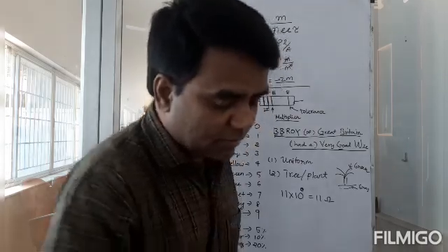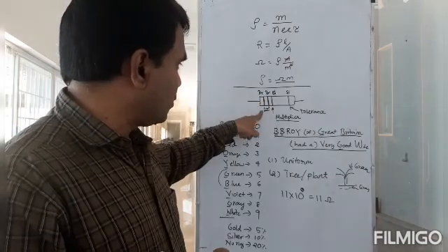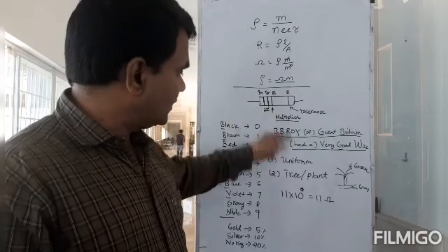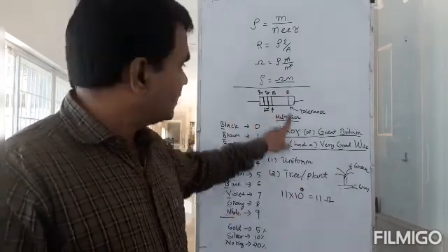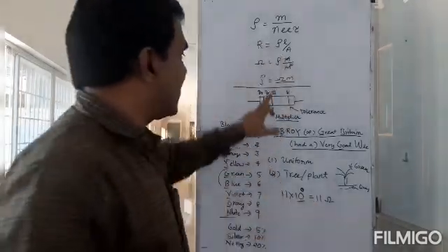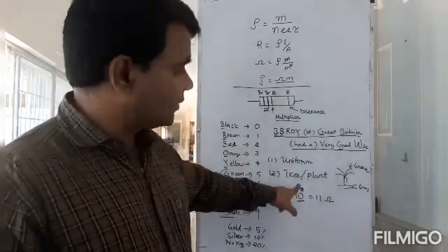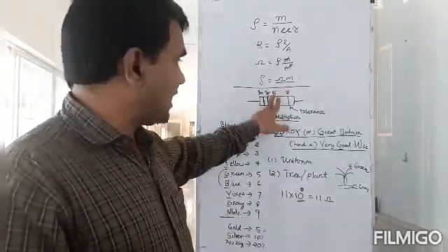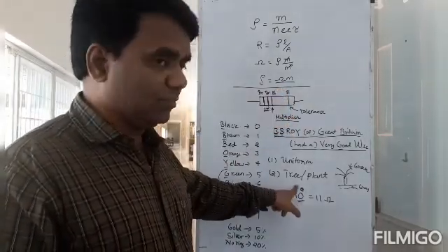So what is the value of resistance here? I have a brown here, I have another brown here. Brown is 1, brown is 1. So 1, 1. Those are the significant digits. And the next one is the multiplier. That is 10 to the power of this color. Because I got black here, I am going to put 0 here. Suppose I have brown again, then that would become 10 power 1, 110. So it will become 110 ohms. But I have black only. So it becomes 10 power 0.